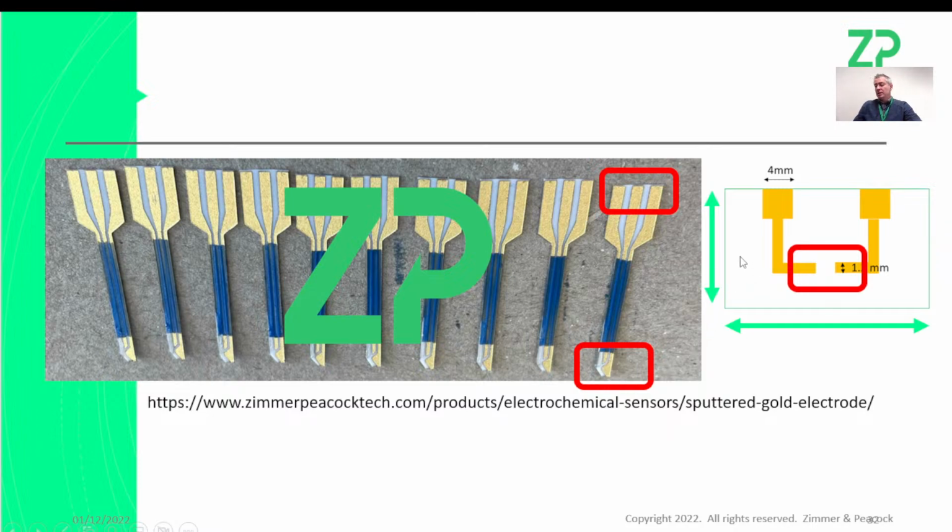The reason I bring that up is when you're manufacturing, the object that I'm looking at here is something like 30 millimeters wide and 20 millimeters width. That really is quite a large object. So I would say that this is not designed for manufacturing because it's actually too big. Often when you're doing vapor deposition of gold, it's quite a batch process. So you want to get as many pieces onto what we call a wafer at the same time. But when you make this piece fairly large, which this is, then you end up with each batch manufacturing very few sensors. So my advice is there's both product design and design for manufacturing.